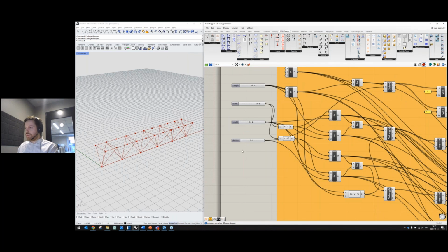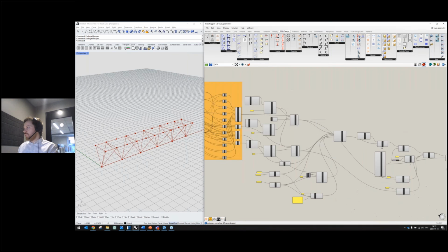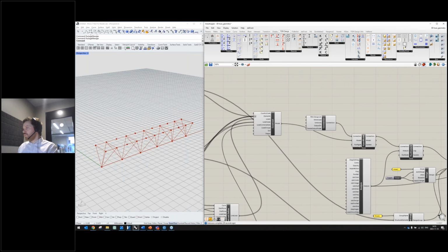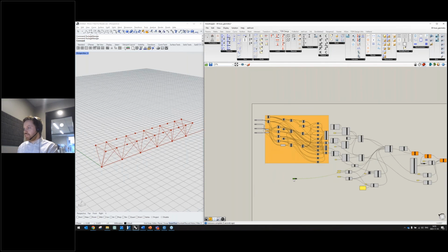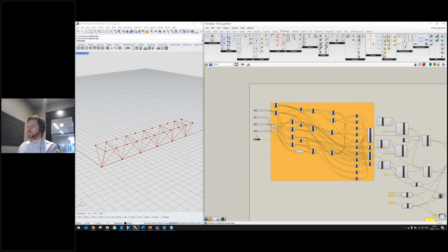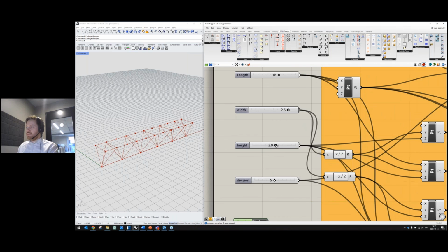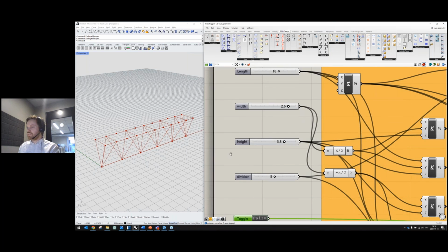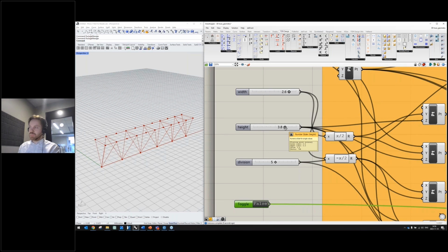But when working with sliders, it's always a good idea to set the run node to false, like this, make any changes and then set it to true, because when I drag on a slider, it will have many intermediate values, and it will trigger analysis each time for each intermediate value.